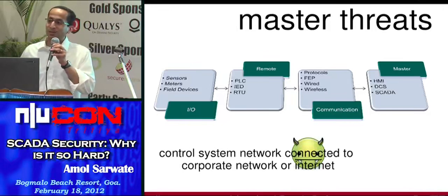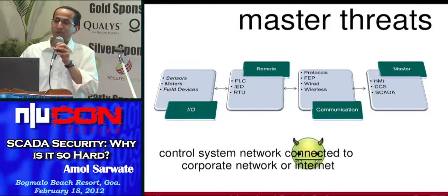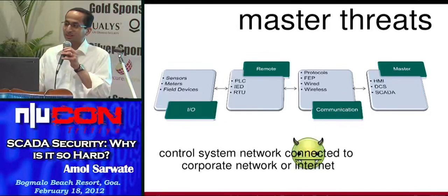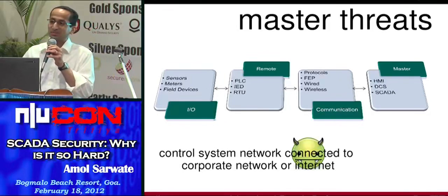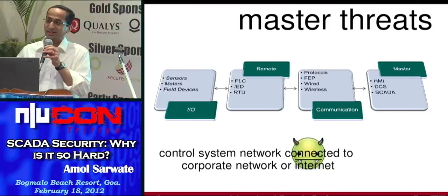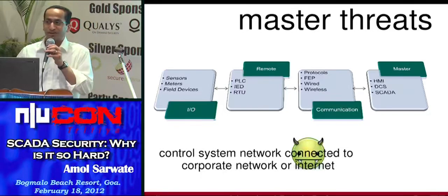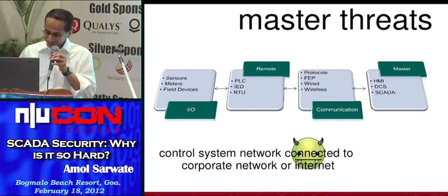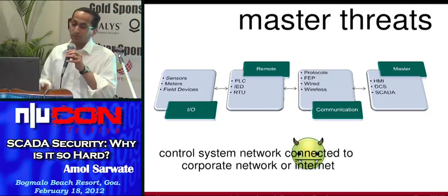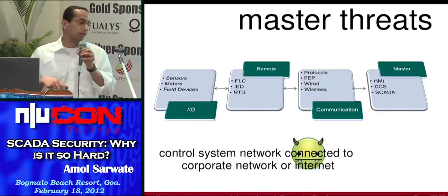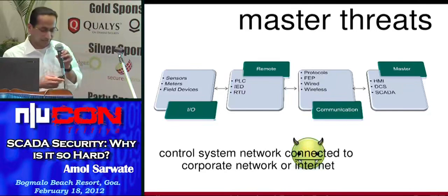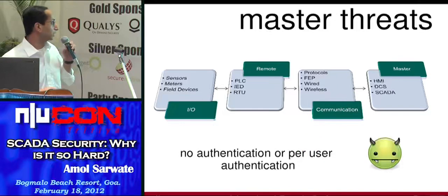And there were Modbus and DNP3 ports. I'm pretty sure if you go today on Shodan and look for PLCs, there will still be some systems online on the internet that you can access, and I don't think there is any valid reason to have these systems online. So yeah, that was the number one threat that we found when dealing with the SCADA master network.